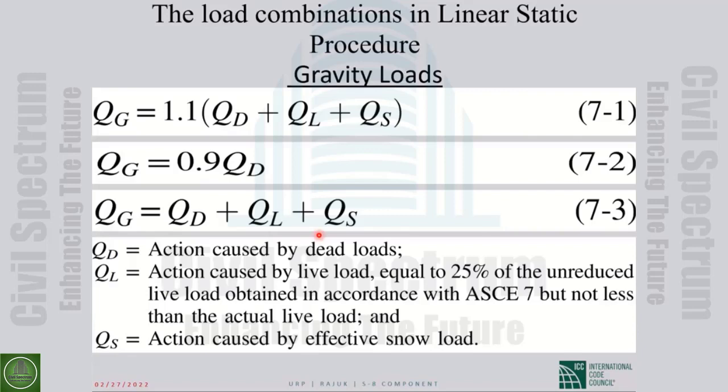So because our estimation of the loads is more accurate, usually there is no need to do the overestimated estimation that usually we do for new buildings, because we are not sure what happens to loading of this new building. Is the distribution of dead load, live load going to be exactly as we expect, as we design, or not? But here in the existing building, you can check and see what is the distribution of dead load, live load. So the number of load combinations is not that much.